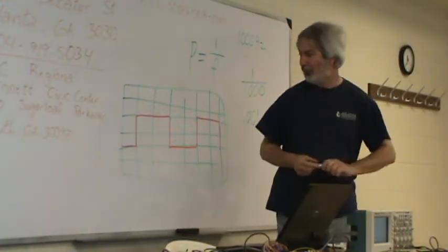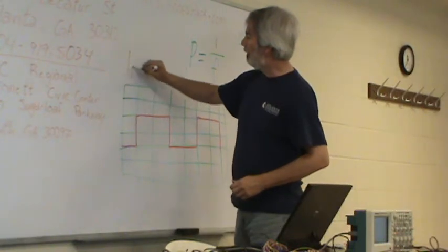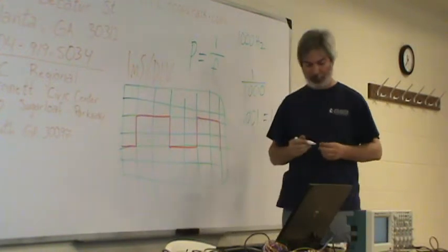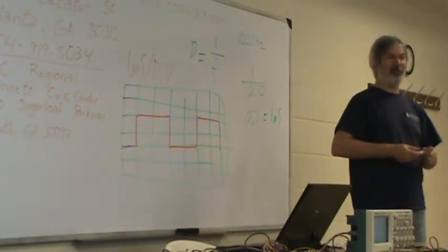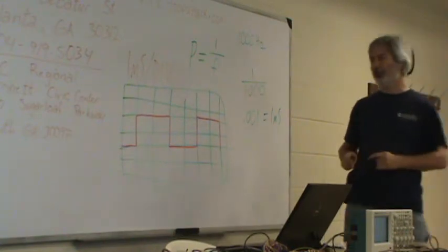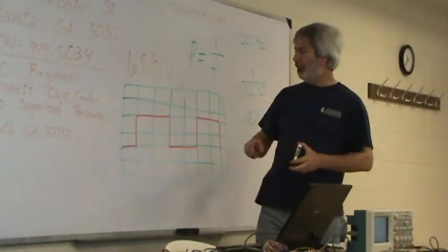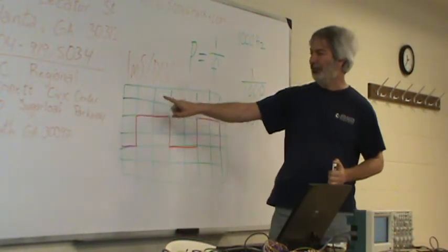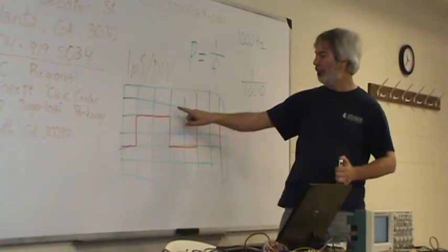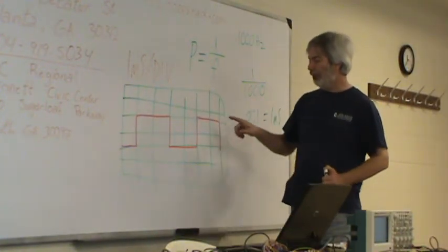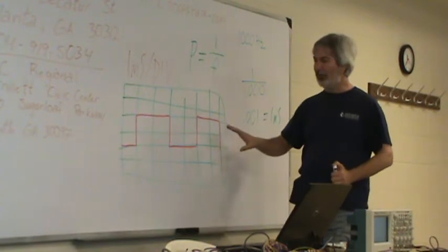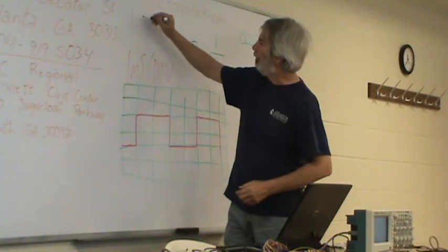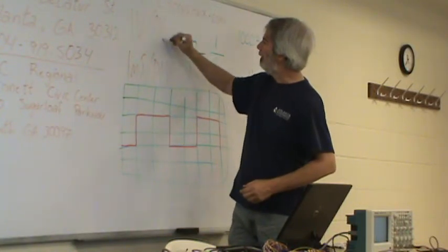Okay, well, let's say you have your scope set up to 1 millisecond per division. Okay, this doesn't work exactly for your example, but we'll get there. So what we have here, we have our scope set for 1 millisecond per division. So that means for every division, that's 1 millisecond. So the information that we can get from this trace right here is, and we'll say we're also set for 1 volt per division.